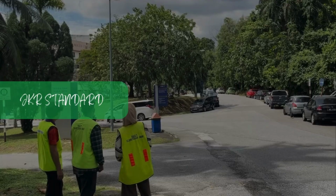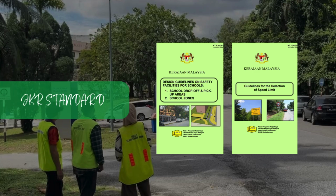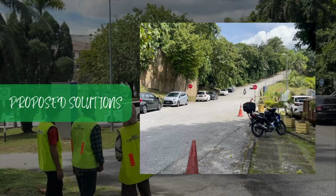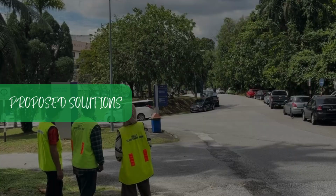So, to deal with the speeding issue, there are a few solutions we can apply based on JKR standards, design guidelines on safety facilities for schools, and guidelines for the selection of speed limit. First, we can install school zone warning signs. According to JKR, advance warning signs should be placed before entering a school zone. In this case, school zone and slow down signs should be installed at the top of the hill. This is important because it alerts drivers early before their vehicles start picking up speed as they go downhill.